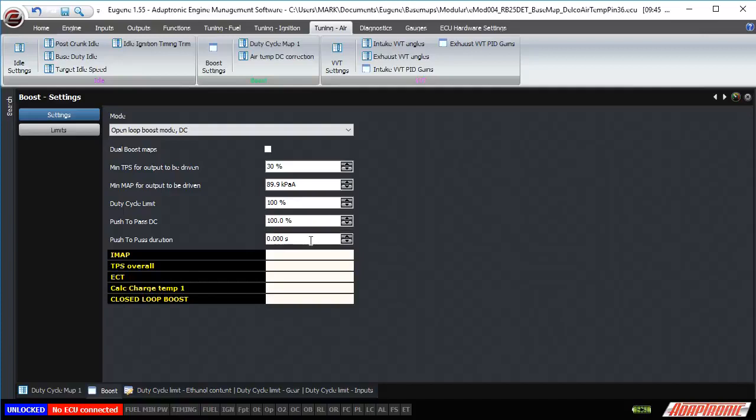This sort of reminds me of the Roger Ramjet cartoon where he takes the proton pill that gives him the strength of 20 atom bombs for a period of 20 seconds. But in this configuration, you can actually set the amount of time. It doesn't have to be 20 seconds. And instead of the 20 atom bombs, you can select what the duty cycle is going to be. So this basically gives you an increased duty cycle for a certain amount of time. It's used for short overtaking periods in endurance racing. That's basically the function for it. It's also called scramble boost by some people.